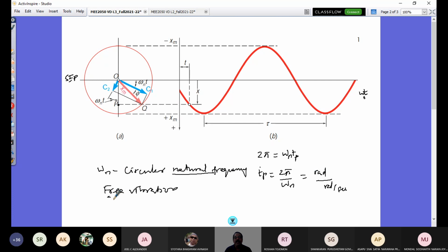Why is it called free vibration? We have seen three cases. You can start the motion by giving some initial velocity at its equilibrium position and have the motion. Afterwards, you are not having any force on it, and we assume that the system is independent of any resistances. So it's a conservative system, and that initiated motion would continue forever and vibrate or oscillate freely, so it's free vibration. So it's called the natural circular frequency. In that frequency, it will be vibrating.